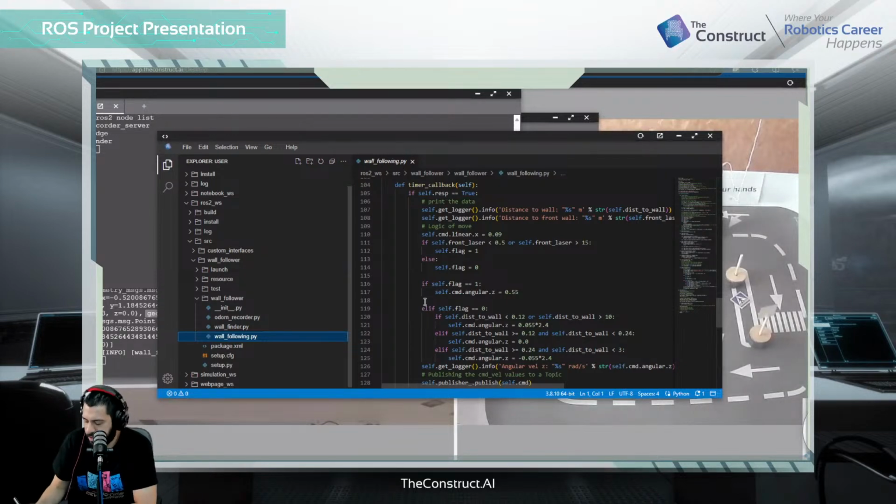Faster, a bit faster. But I didn't use 0.2 or 0.1 because I was worried that the response of the robot was not quick enough and I would have problems with the main code. So I kept the 0.5 seconds, and I tried using a bigger radius. In this case, the exercise asked for 0.05 as the radius, but I tried 0.08. I keep meaning to change that because it doesn't really matter at the end of the day, and that complicates things. Yes, so you could definitely do that.